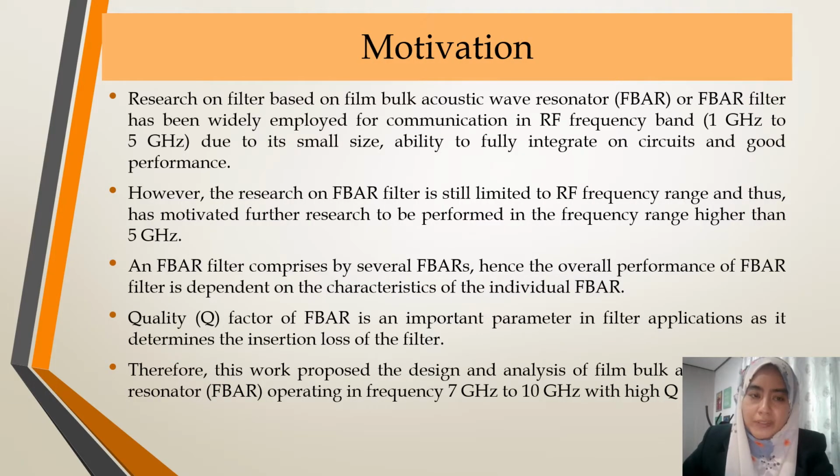The motivation. Research on filter based on film bulk acoustic wave resonator (FBAR), or FBAR filter, has been widely employed for communication in the RF frequency band 1 GHz to 5 GHz due to its small size, ability to fully integrate on circuits, and good performance. However, the research on FBAR filter is still limited to RF frequency range and thus has motivated further research to be performed in the frequency range higher than 5 GHz.